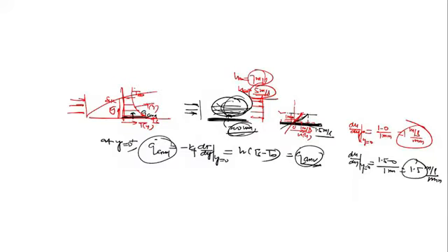This is our gradient. So by increasing the velocity, what has happened? The gradient has increased. And as I told you, if you recall the fluid mechanics lectures, by increasing the velocity the gradient increases, and ultimately we are increasing the Reynolds number. As the Reynolds number increases, the boundary layer thickness decreases.